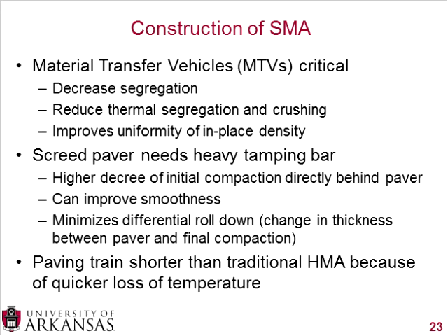Something that I read about in a couple of the articles as well is that people are surprised at how the paving train is quite a bit shorter than traditional HMA. On a traditional HMA job, you'll have your dump trucks come in with the mix. You might have a material transfer vehicle. You'll have your paver. Then a little while back, you'll have your pneumatic rollers, and you might have vibratory rollers and a steel wheel roller to finish. You have this very long paving train. But with SMA, you want to get that material down, and you want it to immediately be compacted, and you don't want to wait a whole long time for that. So your paving train is quite short compared to traditional HMA jobs.